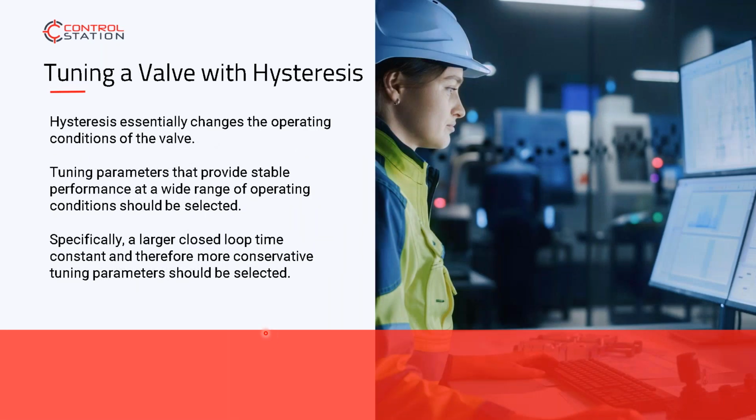The next one here is, how do we tune these? How do we tune for hysteresis? How do we tune for deadband? I've indicated that basically, if you have one of these conditions, tuning for deadband and stiction is about the integral, but hysteresis is about being conservative. That is the rule I would use to segregate them.